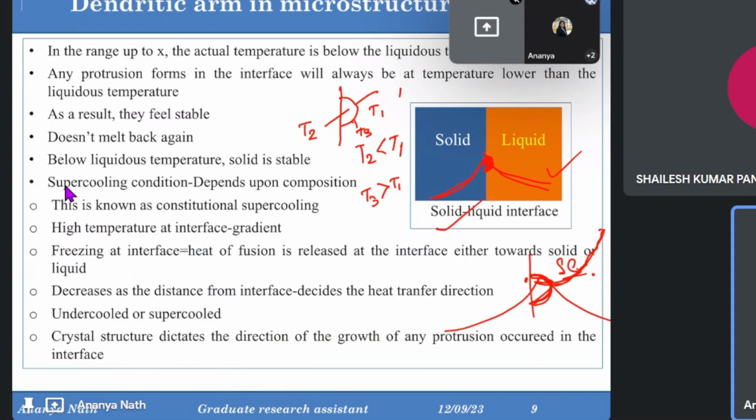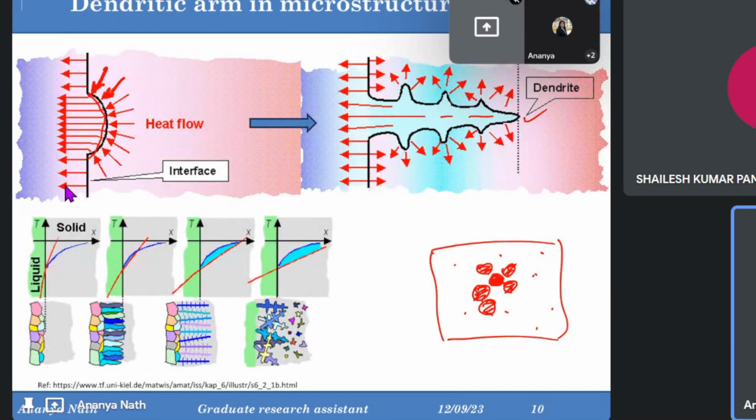So there will be some formation of small grains. The lattices will not try to orient themselves and make some dendritic arms. So there is no such thing. This is why we are talking about slow cooling, where we have sufficient time for these things to occur: finding the preferential sites, and then nucleating, and then growing some dendritic arms. The dendrites will then get broken down, and those broken parts of dendrites will again act as the preferential sites for the next nucleation to grow. These things are different from the rapid cooling thing.